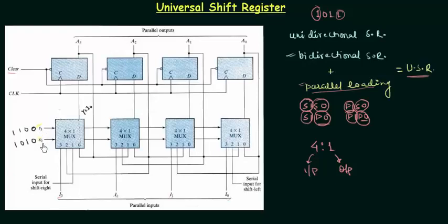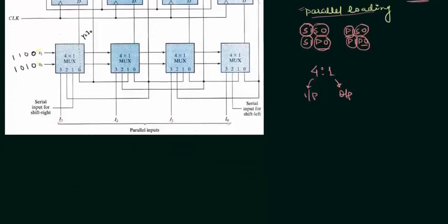That's why they are called selector variables. We can vary them, and by varying them we will select different inputs. So let's make one table in which we will write down these things, and also I will tell you how the selector variables work as the mode control inputs for the shift register. They are not just the selector variables for the multiplexers we are using, but they are also used for selecting the mode of the shift register, whether we want the right shift, the left shift, or the parallel loading. So let's make the table quickly, then we will move to the analysis part of the circuit.